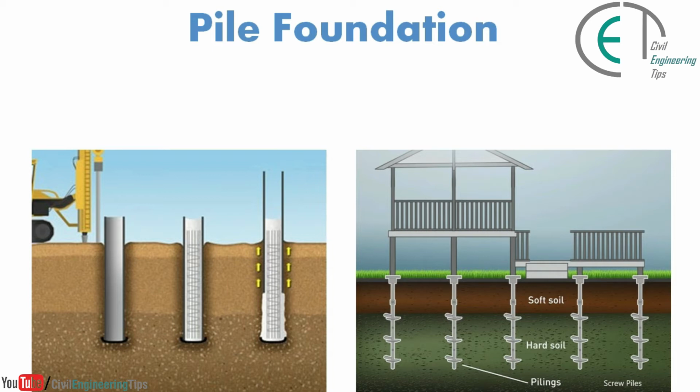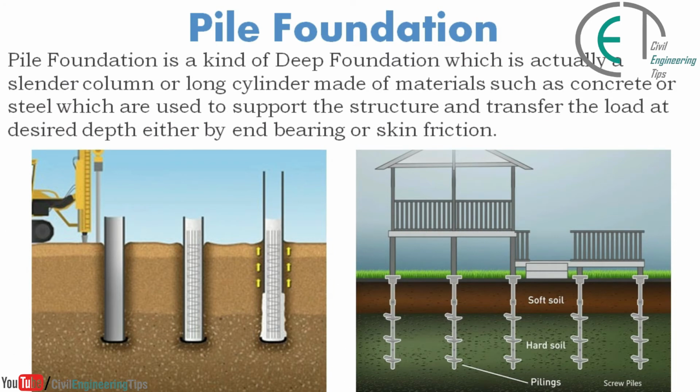In this video, we're going to discuss pile foundation. Pile foundation is a kind of deep foundation which is actually a slender column or long cylinder made of materials such as concrete or steel, which are used to support the structure and transfer the load at desired depth either by end bearing or skin friction.